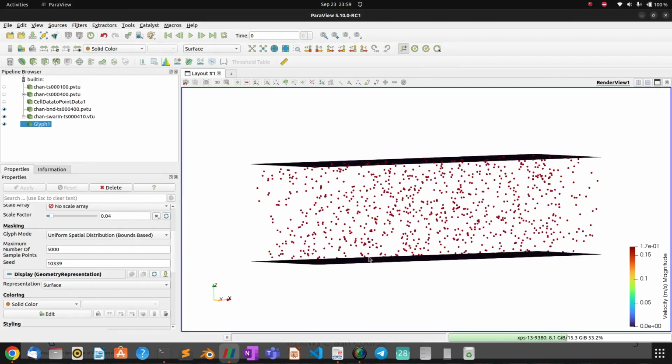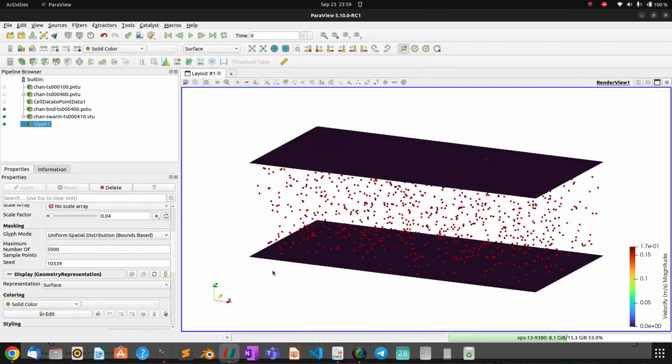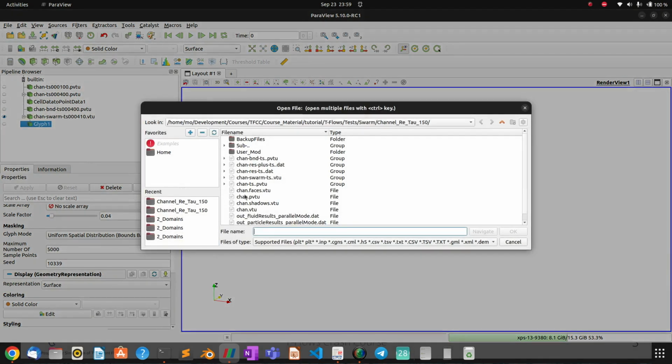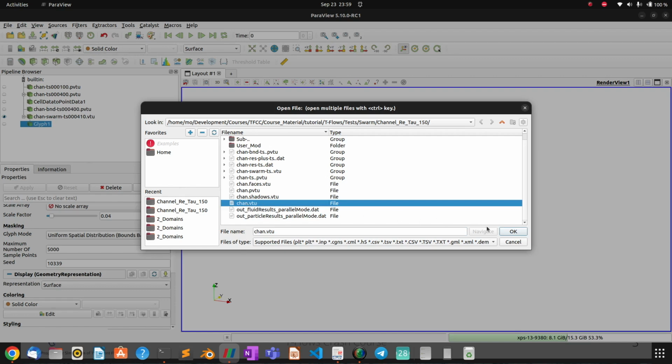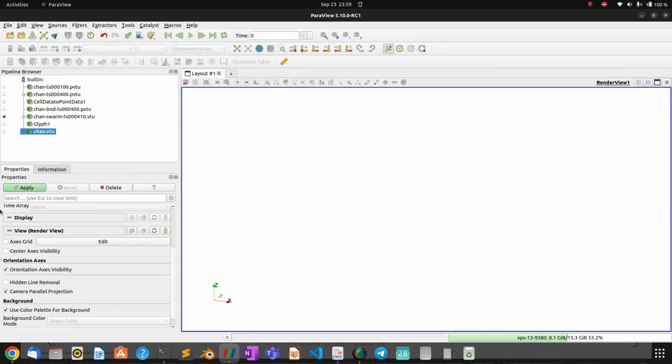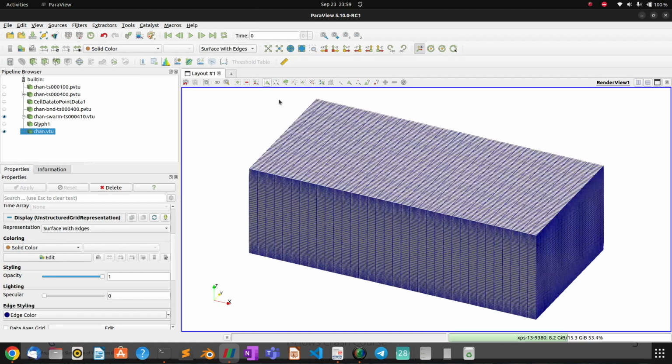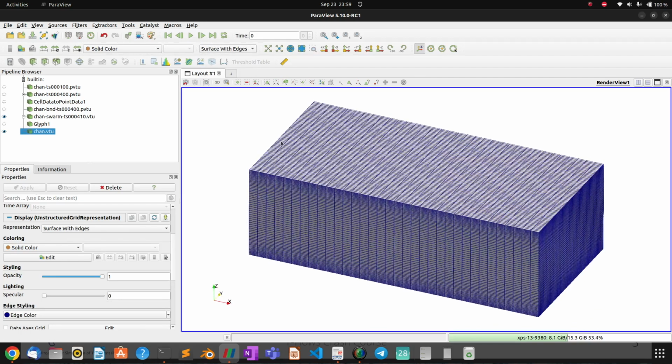So it's a good representation if you like it. If you don't, then you can maybe switch the boundary file off and go to maybe a VTU file. A VTU file is just a geometry file that was created at the very beginning, before even dividing the domain into 4 subdomains. And if you hit apply, then you have the domain which contains the mesh also. So you have the whole domain which contains the mesh.